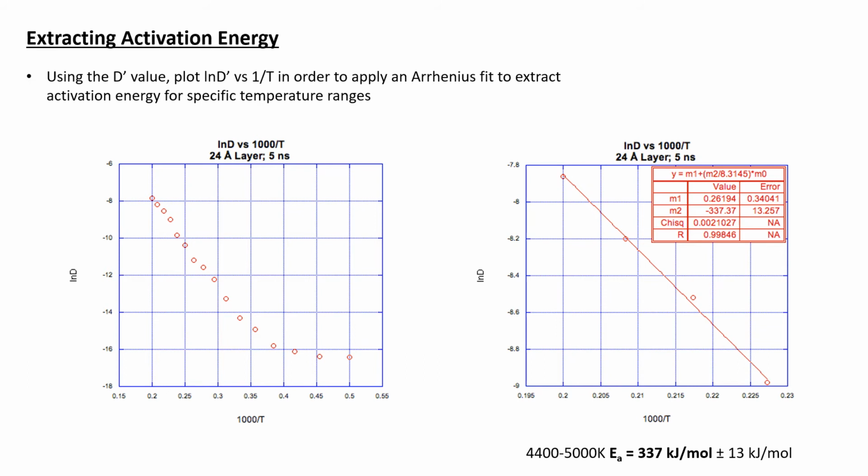At lower temperatures, the diffusion coefficients don't become significant enough until after the kink in the upper 2000 Kelvin region. Because of this, I usually focus on the upper temperature regions in which more linear patterns can be seen, and this is most likely due to a phase change between a more solid phase into a more liquid phase in the silicon nitride layer.